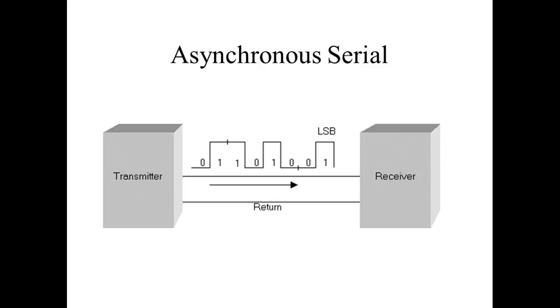The problem we have with this became known as single-ended interface, which means we have one wire that handles it. We call it the data wire, and then one wire would be considered the return, usually referenced to earth ground. Now, the problem we had with this single-ended interface is that y'all know what magnets do when a magnetic field passes through a wire. You know what it does? It tries to induce voltage. And how much voltage you induce would depend on the current carrying capabilities that you're sending it through.